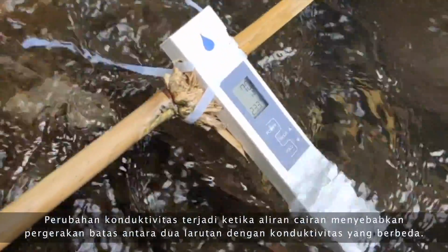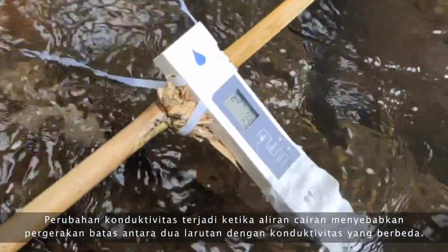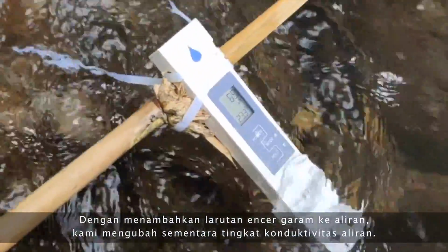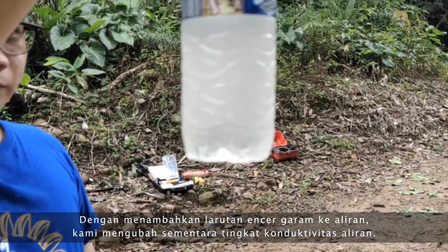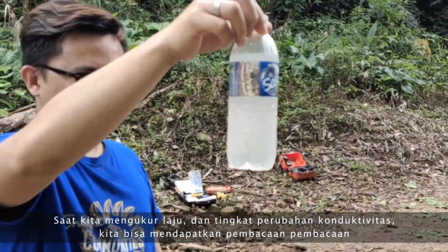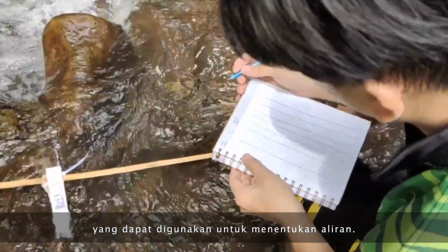Conductivity changes occur when liquid flow causes movement of the boundary between two solutions of differing conductivity. By adding a salt-diluted solution to the stream, we temporarily change the conductivity level of that stream. As we measure the rate and level to which the conductivity changes, we are able to plot the results along a bell curve that can be used to determine the flow.